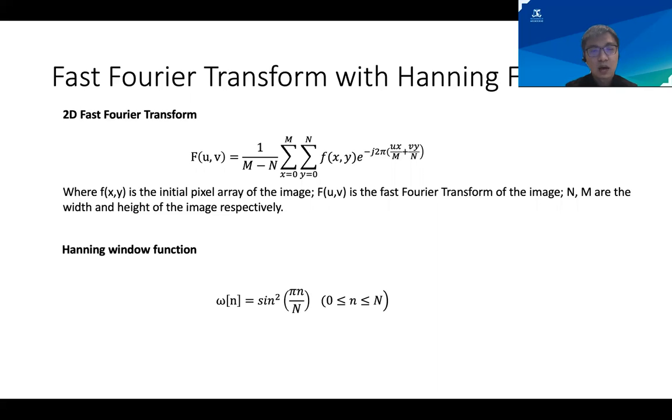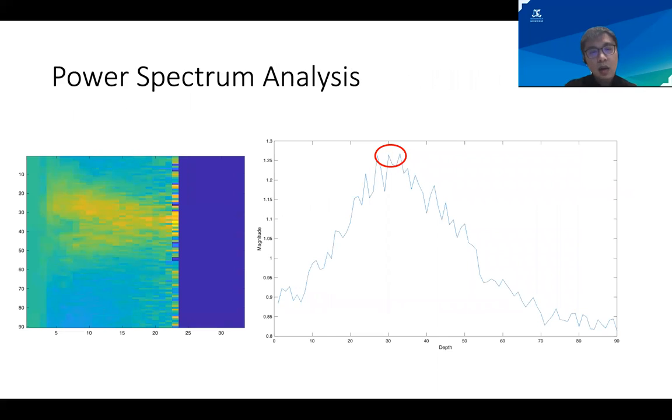And so I segment several time intervals which contain stable and periodical signals. To reduce spectrum leakage, I use the Hanning window function during the signal segmentation. So in my case, the golf ball images are an example. In the frequency domain, there is a peak in the power spectrum with high power density at a pixel. A preliminary depth map is acquired from the initial power spectrum analysis.